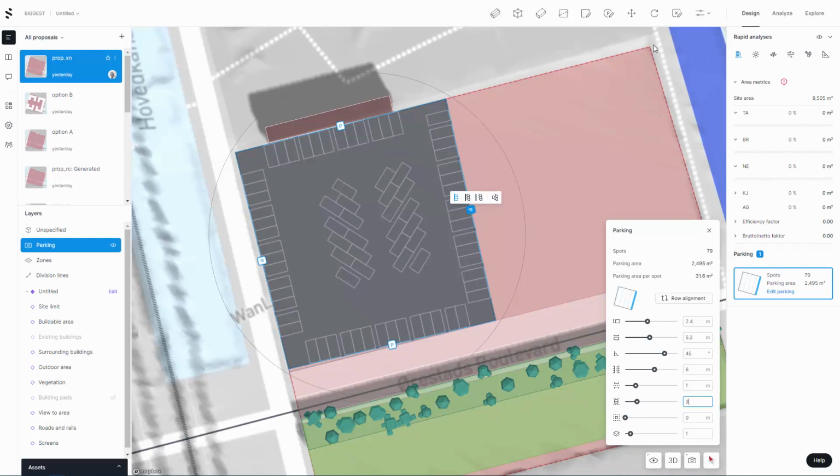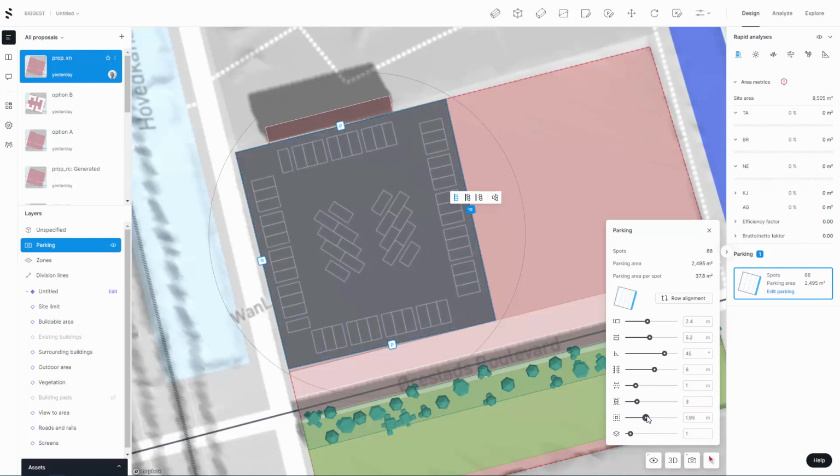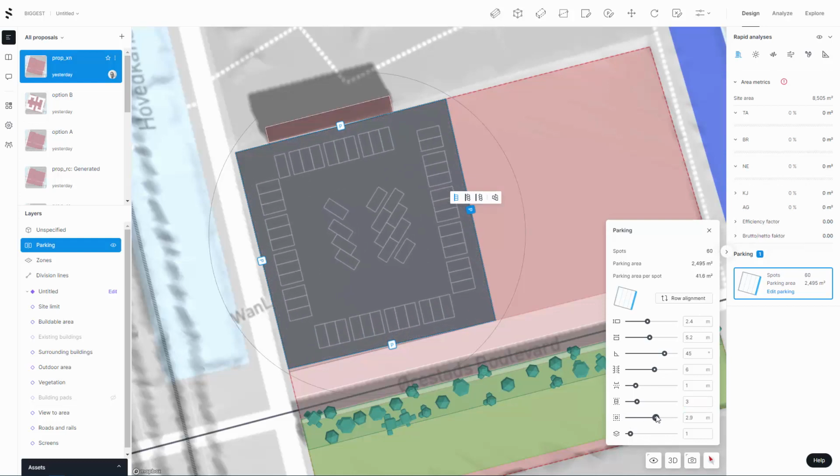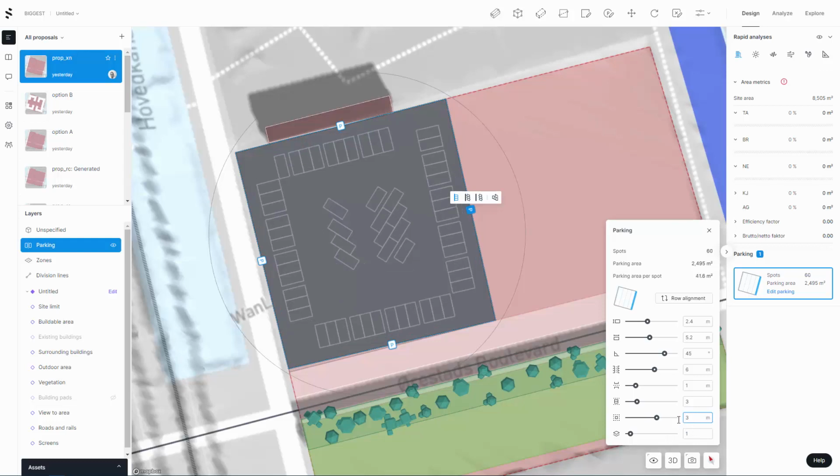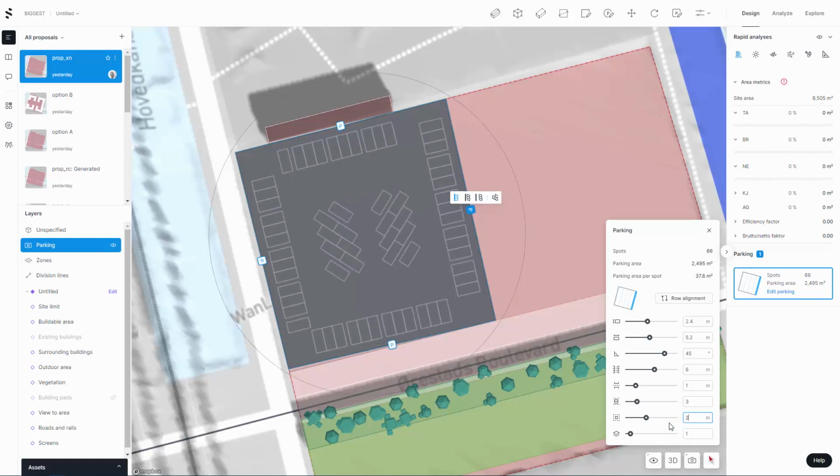Again, if you're building next to the water, you may end up getting some seepage in here, and you'll need to have a channel around the edge. For some apartment buildings, it's good to actually have a setback here. You can put in storage cages for the tenants at the end of the car park, so they can add more value. Again, how many spots will you sacrifice if you have that setback for a cage? So we're maybe losing six spots. So we have a 3 meter cage, and we get an extra 6, so we have a 2 meter cage.